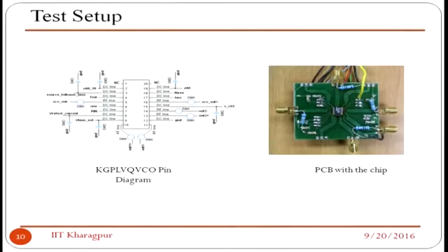All this connection is the PCB, which should be matched; special RF PCB software is available, where you have tapered junctions. So you have to taper this so that impedance is matched. It is not a standard PCB where the interconnects are straight lines, but you need a tapered one so the impedance gets transformed. These are the few things you have to understand. And you have used simply a DIP package, which is not good. You have to use QFN kind of packaging for high frequency and so on. So this is the design, and the PCB and the chip are placed on that, and then we are measuring that one.